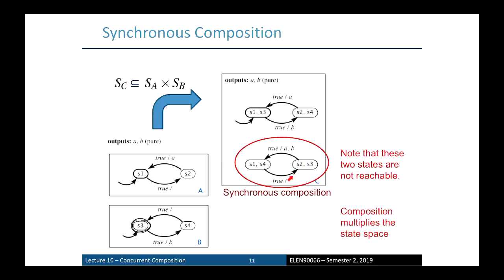Right? So we can explicitly show that if you were in that state, maybe there was a hardware failure or something funny, and it ended up here, you could actually be in this loop forever, going between these two states here. So excusing failure, this machine will output AB, AB, AB, AB forever, and these are unreachable states. So you can formally prove that, all things working, those states should never be reachable, okay? Right. So that's the easy one, the synchronous machine.